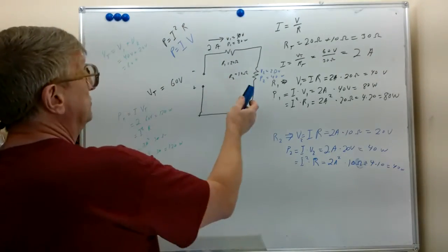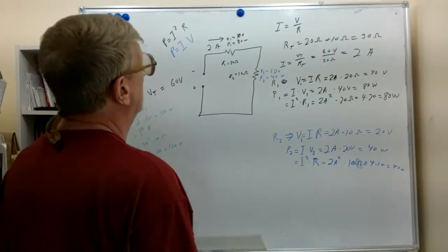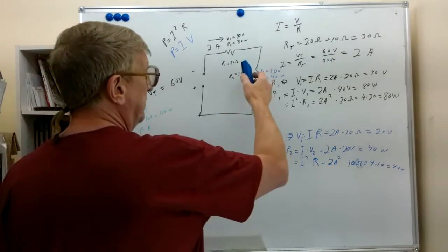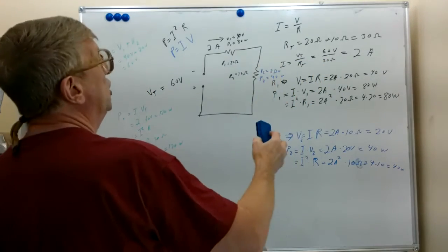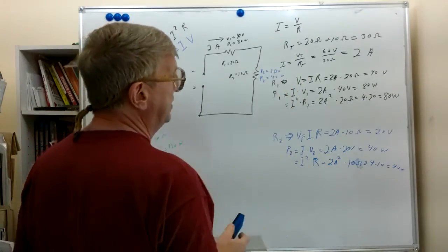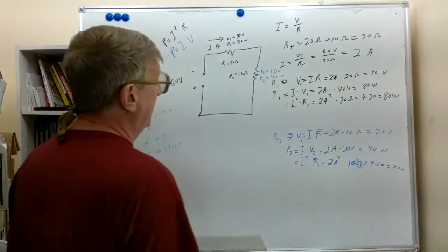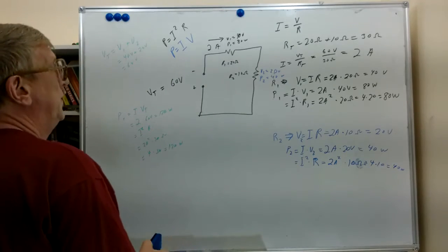We started out, we had the resistances, we had the voltages, we did not have the current, so we used the total resistance formula to come up with the total resistance. We divided the supplied voltage, VT, by RT, the total resistance, to get 2 amps. And that gave us all the information to solve anything we needed to know.